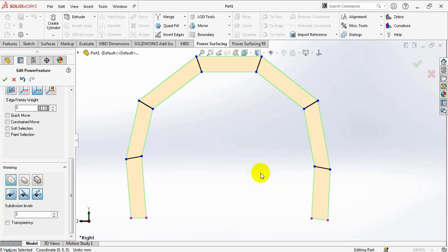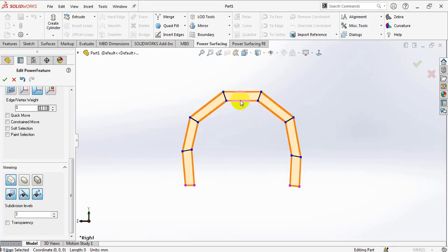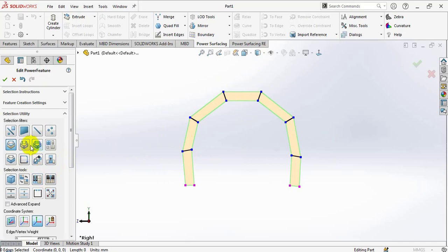Second, here we're going to make some faces again. So I'm going to select the edge loop here, but not all. I don't want to select all edges here. I just want to select this edge only. So you can select Stop at corners when selecting edge loops, and then you can select a single loop.